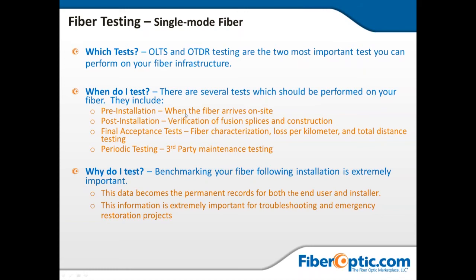So what tests? And I've kind of implied the infrastructure. And when do you test? Well, we mentioned pre-installation. Boy, that's the real one. On the reel. Post, you test it to verify the value of fusion splices in construction. The final, let's call that the big documentation day. Your client's going to want to know a complete fiber characterization, loss per kilometer of distance through the fiber, total distance loss testing, and details of each splice and connector pairing.